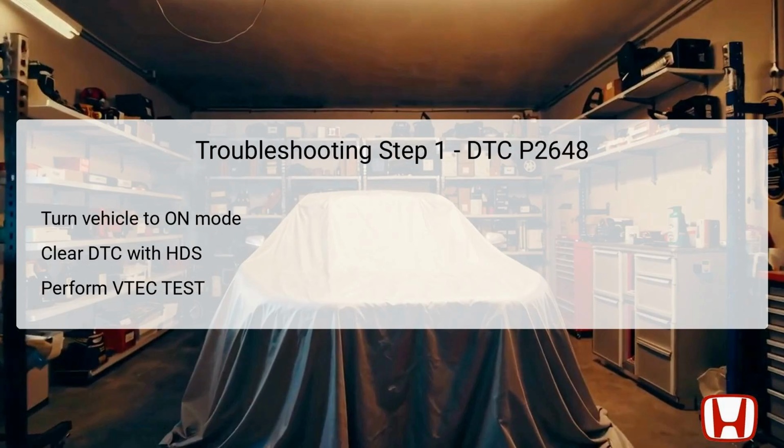The first step in troubleshooting DTC P2648 involves turning the vehicle to the on mode, which energizes the vehicle's electrical systems without starting the engine. Next, utilize the Honda Diagnostic System, HDS, to clear the DTC. This may involve confirming prior issues that may not be immediately apparent.